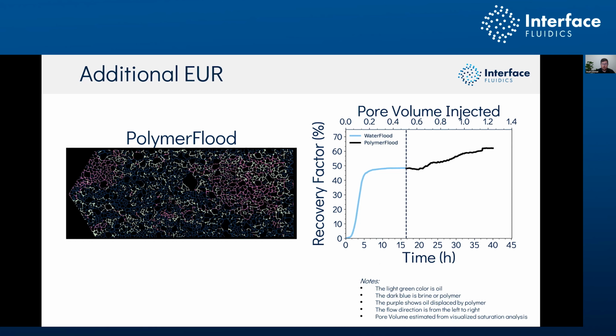So this goes beyond just understanding recovery factors. This goes into understanding the amount of oil that is trapped, the mechanisms behind the trapping in your residual oil, and can I mobilize that residual oil? And we see different behavior in residual oil trapping based on many different factors, but chief among them, fluid properties and the porous media itself. So being able to recreate the porous media and use real fluids was critical to understanding the displacement mechanisms in this scenario.